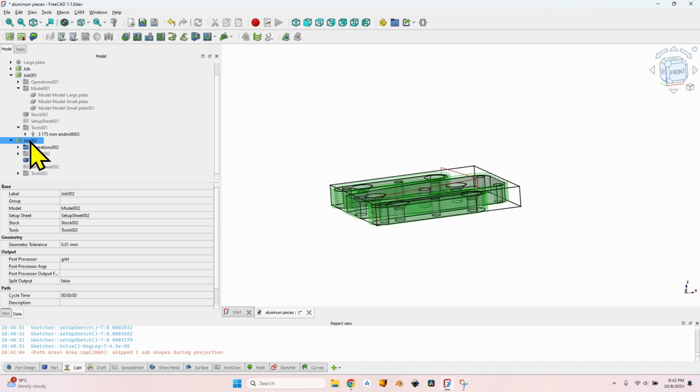Of course, there are formulas based on the shape of the tool bit. For sure they are useful, but what is the most important part about setting the feed and the spindle speed is the way your machine is built, the rigidity of the machine, the hardness of the material. So there's not a universally valid formula, there's not a formula that you can use for any type of material.